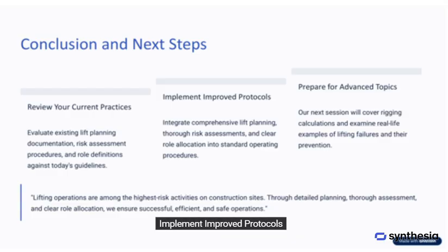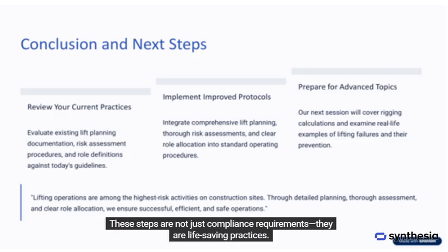2. Implement improved protocols. It's time to raise the standard. Make sure your organization integrates comprehensive lift planning into every lifting activity, thorough risk assessments for every unique operation, clear role definitions into your standard operating procedures. These steps are not just compliance requirements, they are life-saving practices.